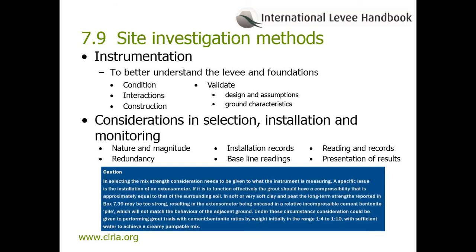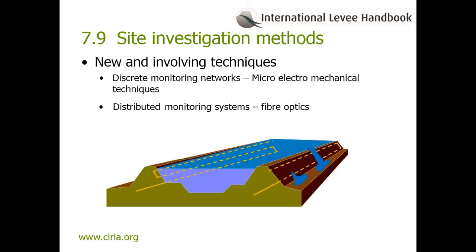There may be a need to use grout mixes with a much lower cement-bentonite ratio. Grout mix trials should be undertaken to ensure its strength is compatible with the surrounding soil and the type of instrumentation to be installed.